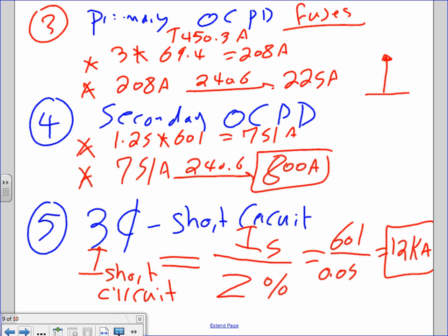If it's not a standard here, Adam, we went up again. Can you guys see that? If it's not a standard, you go up. Why do you go up? Because if you go to table 450.3A, it will tell you on the primary and the secondary in this scenario, if you don't hit a fuse, do not get mad at Chad, just go up. Cool?